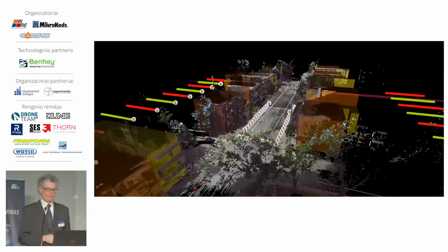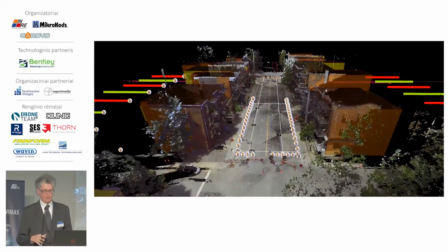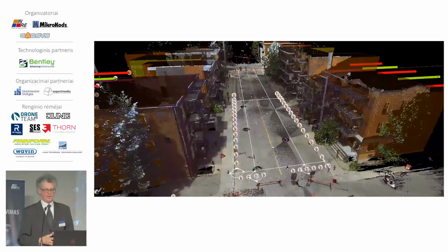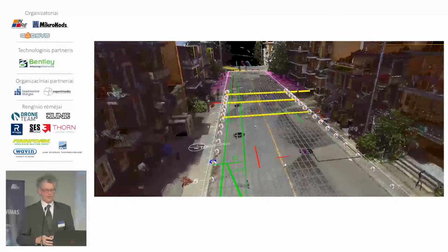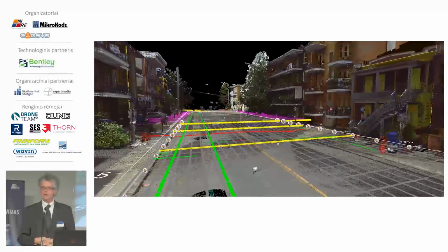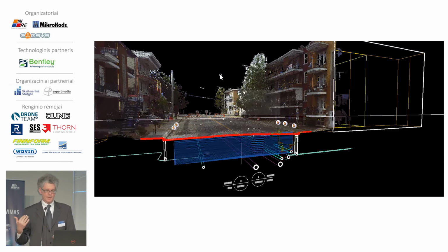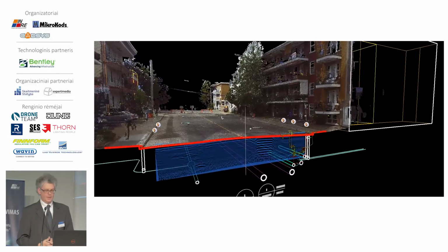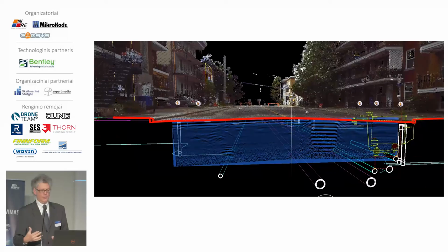Now I'm back referring to the point cloud data, which you all know very well. So this is before the reality modeling, but the beauty of the point cloud data basically is that it's capable of visualizing quite well the underground infrastructure. So we can open up sections, for instance, and then display what we have as an integration between the point clouds and all the network below.